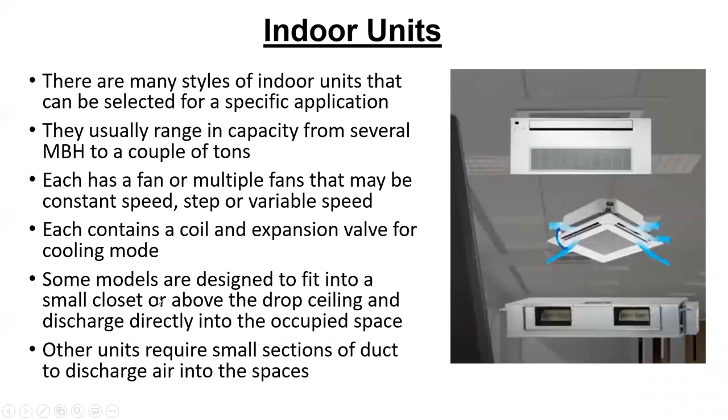There are many styles of indoor units that can be selected for a specific application. They usually range in capacity from several MBH, thousands of BTUs per hour, to a couple of tons. Remember, 1 ton is 12,000 BTUs an hour. Each has a fan or multiple fans. It may be constant speed, step, or variable speed.